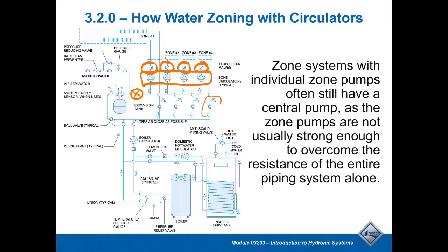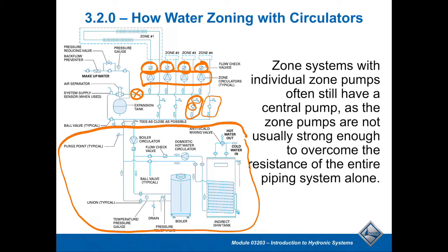The other thing that is interesting on here is that with this piping arrangement, you've got to have the ability to have an air purging system. So this little combination of a shutoff valve here and a boiler drain here allows you to purge the air out of those loops when you have to do service on each of those. You'll notice that every one of those has that. Everything else down in this region is very much the same for either one of those two systems that you have to be aware of. But there again, you just have to watch that to see how that is.